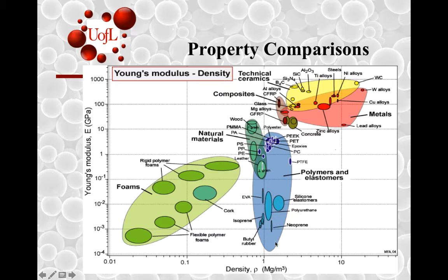Again, look at the Young's modulus. It can go from elastomers all the way up to polyesters. Here are some natural materials stuck in as well. And at the top, in the yellow shaded bubble, are the family of materials which are ceramic, technical ceramics. And then you have composites thrown in over here. GFRP, glass fiber reinforced plastic, CFRP, carbon fiber.